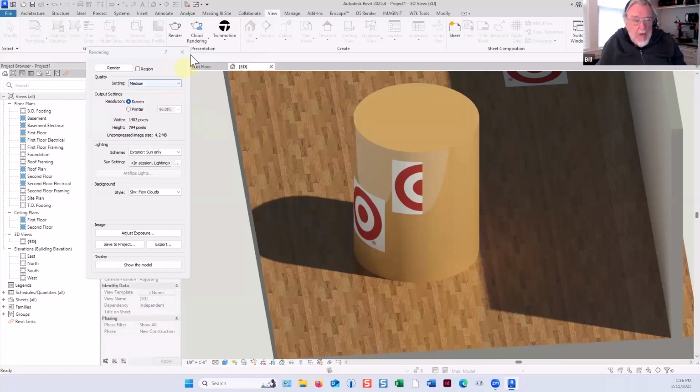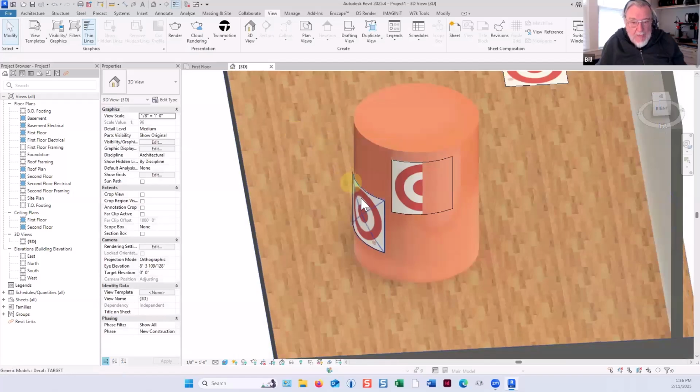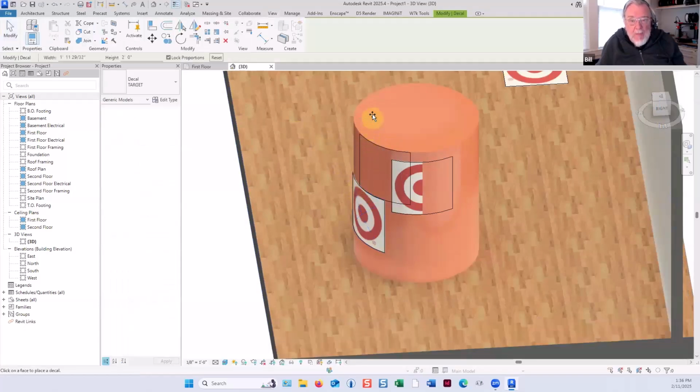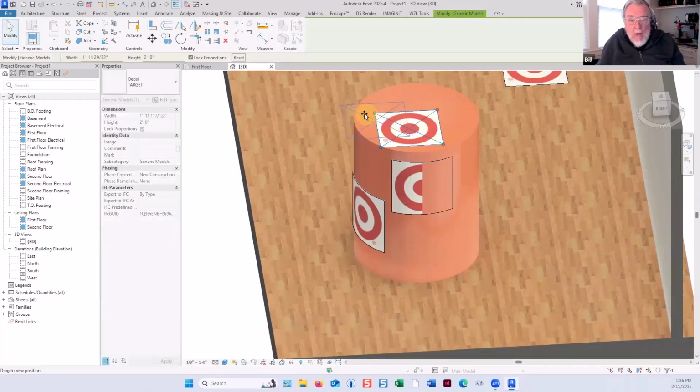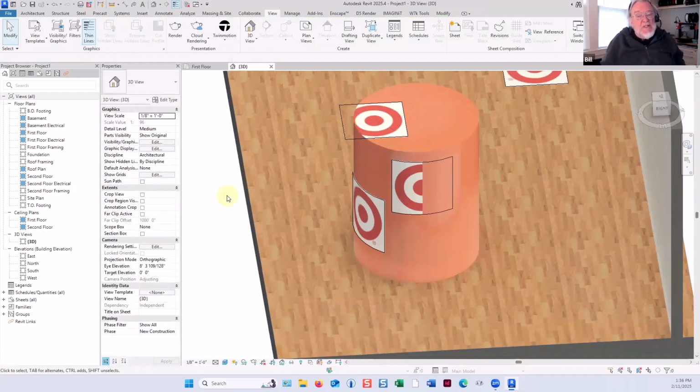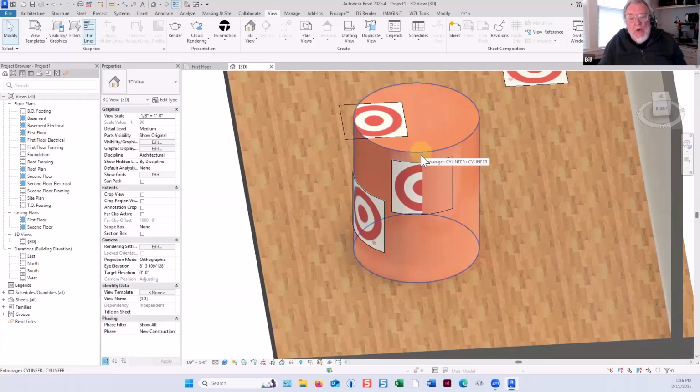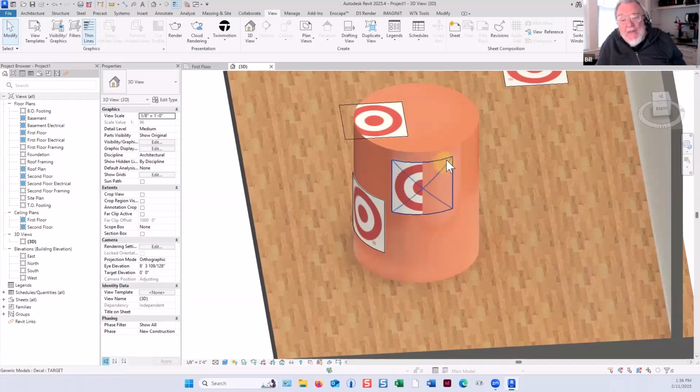Oh, this is interesting. Let me show you what's happening, and we can maybe fix this. If we cancel that, and then pick this and type CS, and put one on the top, you'll see that we only see it to the extent that it overlaps the surface it was applied to. So here, Revit has made essentially two semicircular surfaces, and this one falls off the top surface, so we don't see it. This one falls off this front surface, so we don't see it. So I think I can put one on the back surface and slide it over so we have two halves.